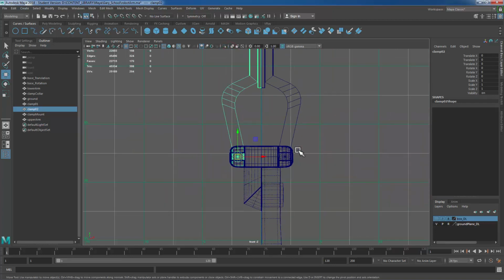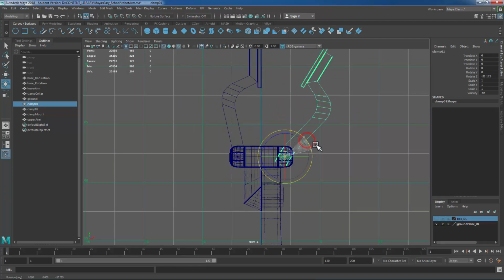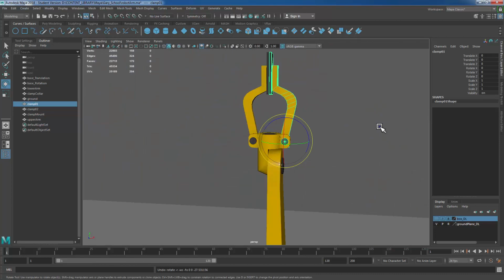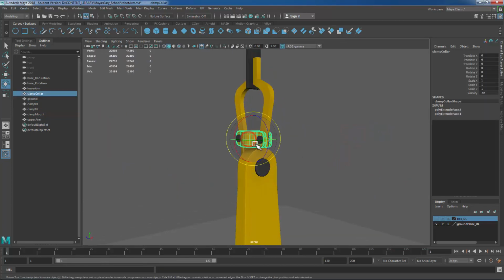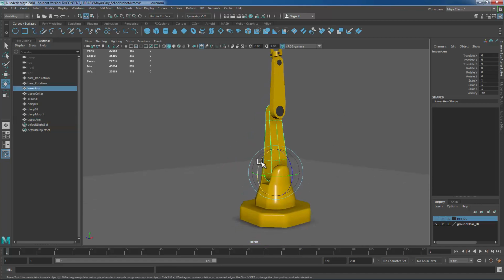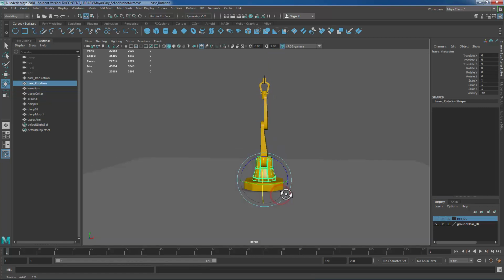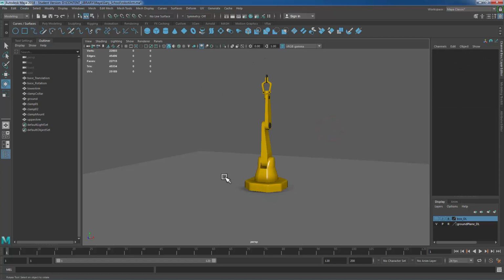Okay. And we can double check if we want to that these all work exactly the way we expect them to, which is a good rule of thumb after you've done this. Before you actually start the constraining process, double check that you've got all your pivot locations set up correctly, that you don't have any transforms, and all your object history has been deleted, because that's going to be a problem when you come back. All right, so now that that is done,